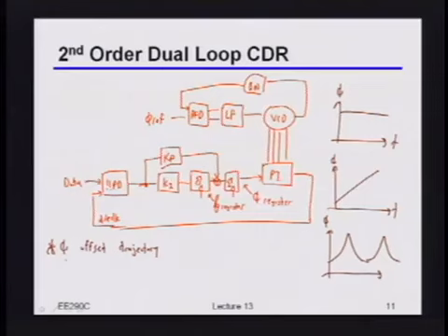Supply? Well, no, okay, I mean, you could vary the supply to make this happen, but it turns out that people want things to look like this. Again, they'll actually work really hard to make their PLL on the transmitter side intentionally do this. So any thoughts as to why you might want to do this? Oh, is this like spread spectrum clocking? There we go. It's spread spectrum.